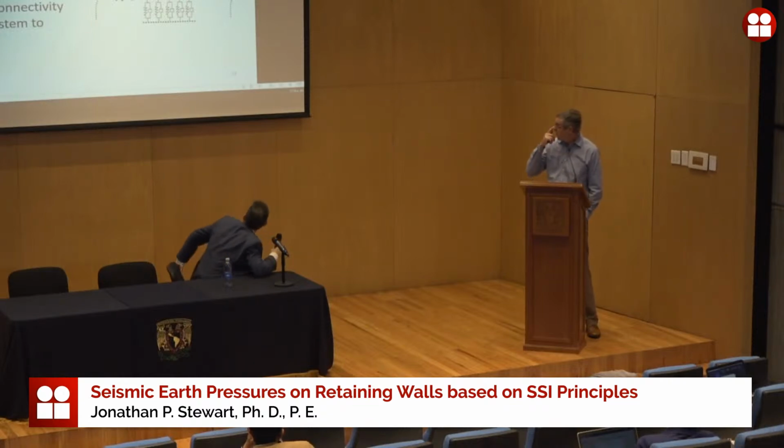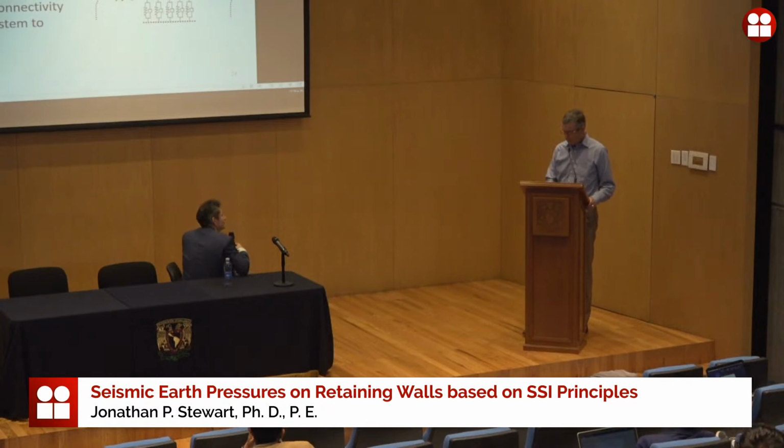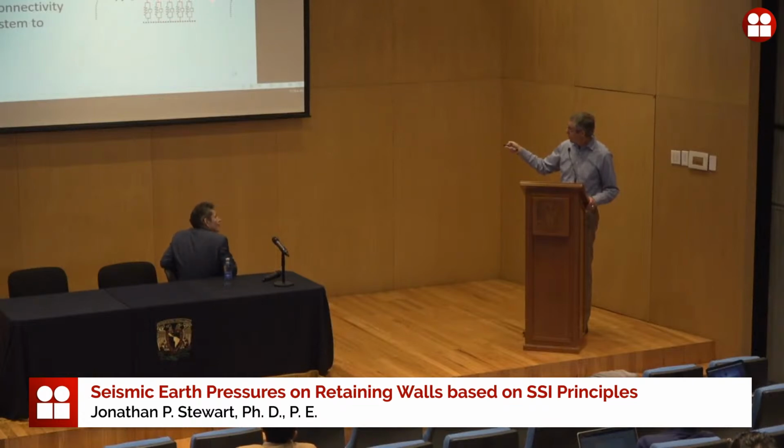So I'll go back to the schematic here. There you go. So, yes, if you have piles, they would be down here, right? So the piles would be part of the foundation system supporting the wall and the base slab here. And in this context of an inertial soil structure interaction analysis, it's actually pretty simple. The piles would be what governs the properties of these springs and dashpots. So they would just become a lot stiffer than if it's shallow only.